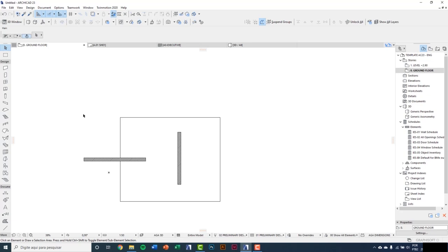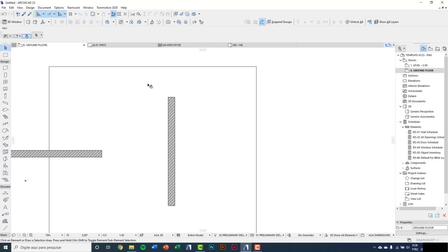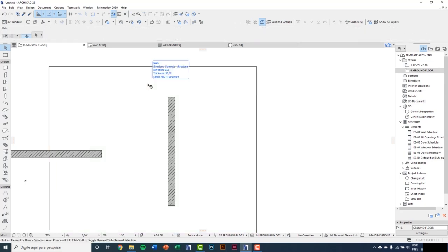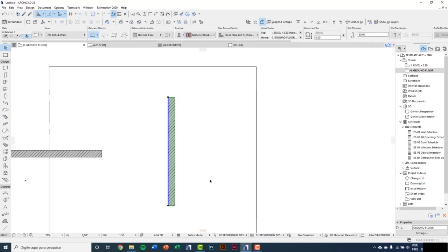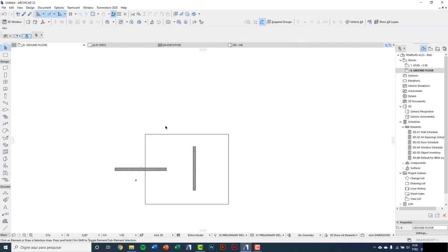For example, I could want to do a rectangle selection in this wall, but making a click, it selects the slab. So I press the space bar to turn off the magnet temporarily, and then I make the rectangle around the wall. And to add selection, you can hold the Shift key pressed, and then you click to add selection, and press ESC to deselect all. And also I have the marquee tool.